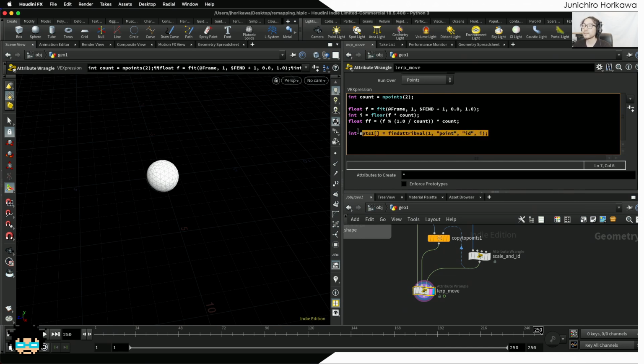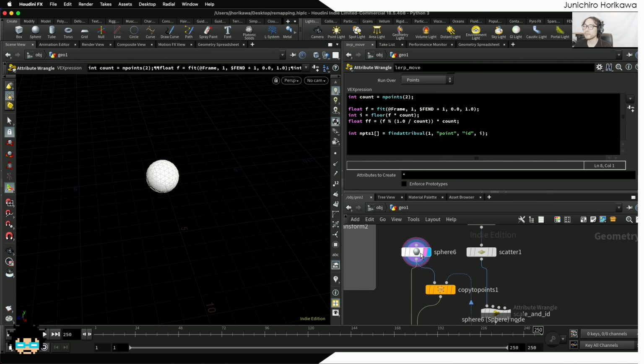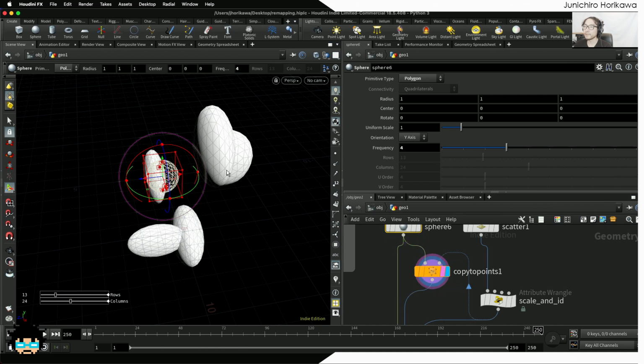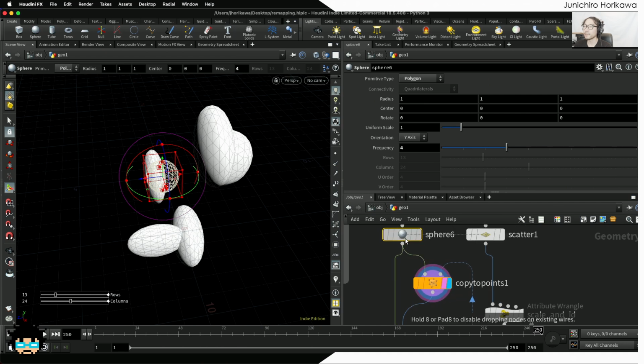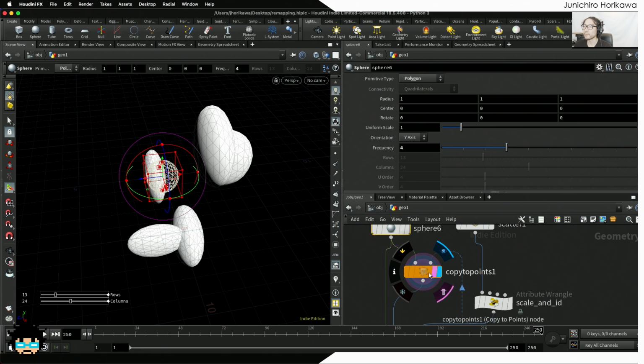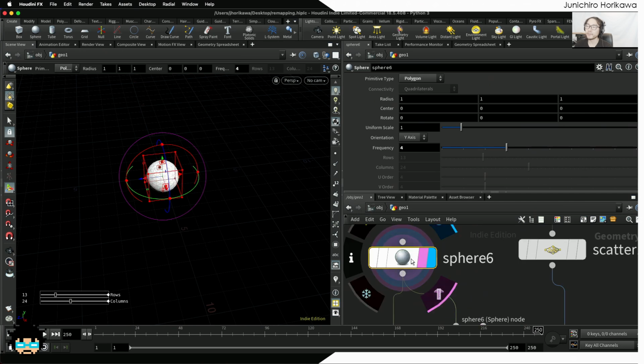Now as a result, you'll get a number of points which construct a sphere, and out of this point array, I only want to retrieve one point number. Since we are using a point attribute together with the base sphere, which shares the same point numbers as the spheres that I have created here, because right here I have just copied this sphere as a template using the copy to points, all the copied spheres in space share the same point structure, or same point numbers.